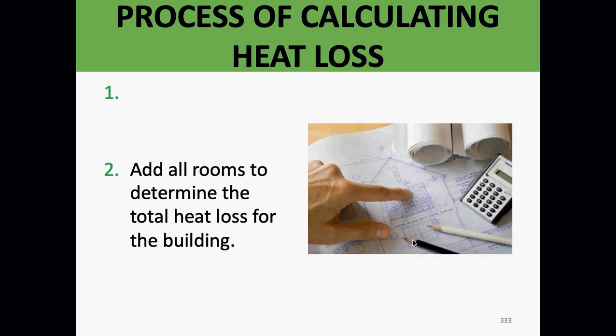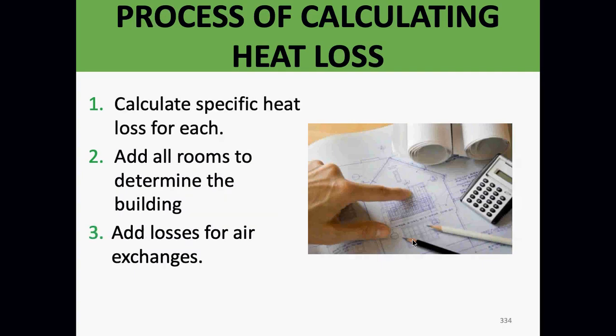Why do I care about entire building heat loss and heat gain? Why do I need that number? Anybody? Why do I care about heat loss, heat gain for the entire building? To size your heating system, I would imagine. Yeah, I can't size the main system, the furnace, the air handler, the boiler on a room by room basis. I need a total.